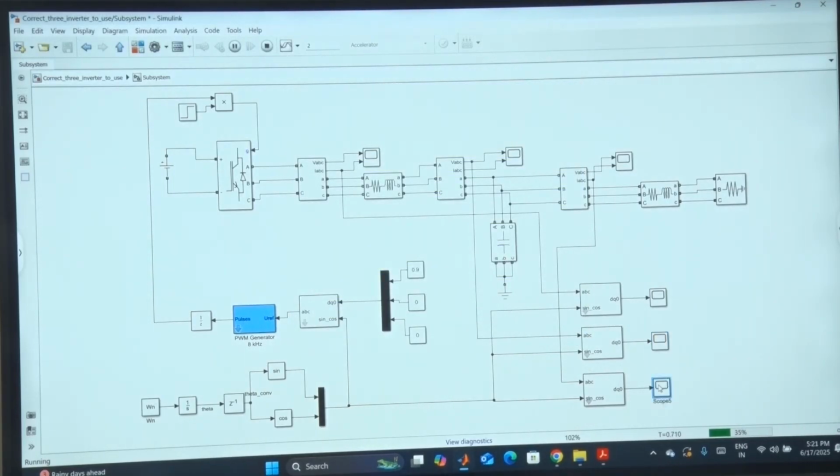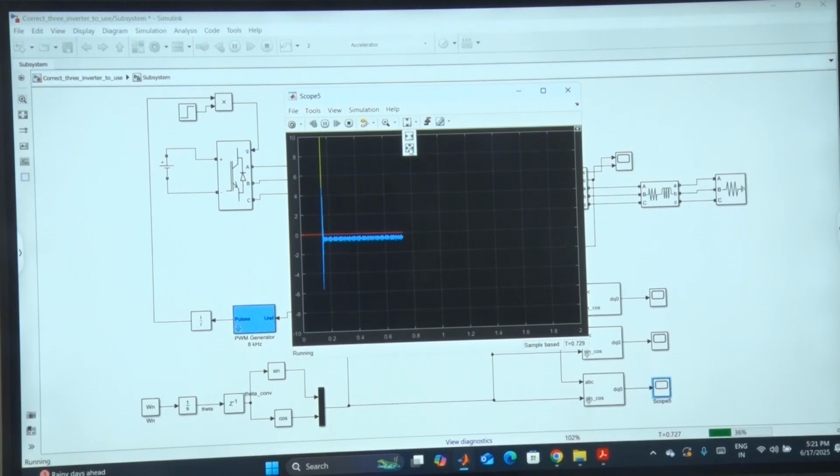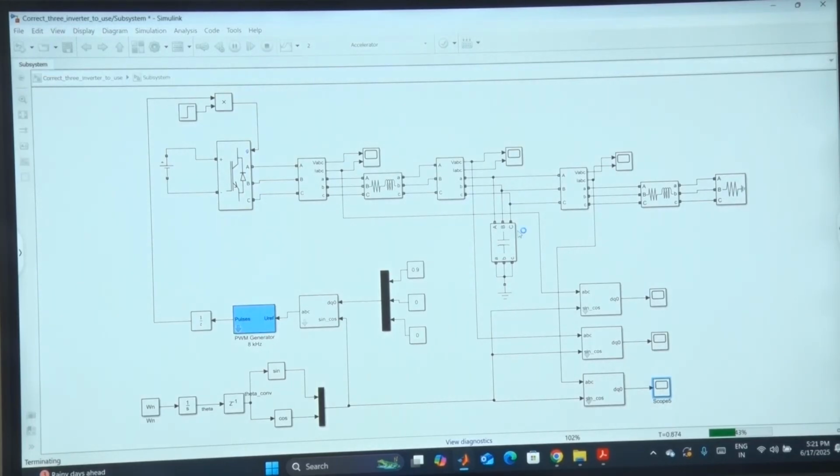Likewise, output current, IOD, IOQ. Output current will definitely have less ripples because the high frequency current component passes through the capacitor. So the output side is more filtered, therefore it has less ripple. So you have IOD, IOQ. Now when we measure the power, we measure output voltage into output current. So the last two we use. While in the control we have ILD star, ILQ star. There we'll use the first current measurement. Okay. So now let's see how we measure the power.